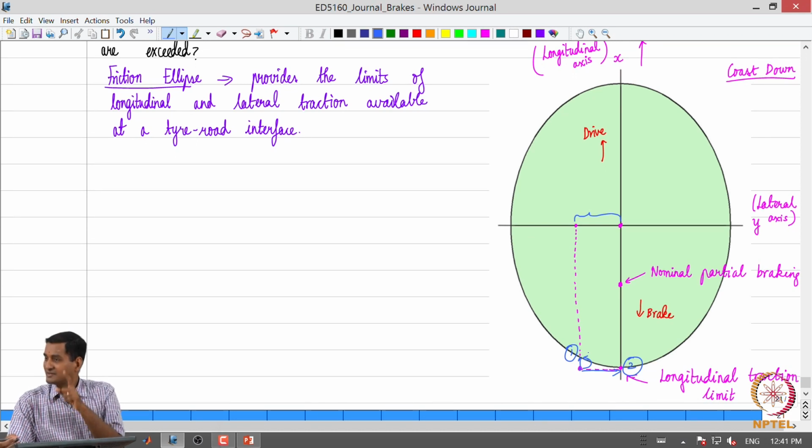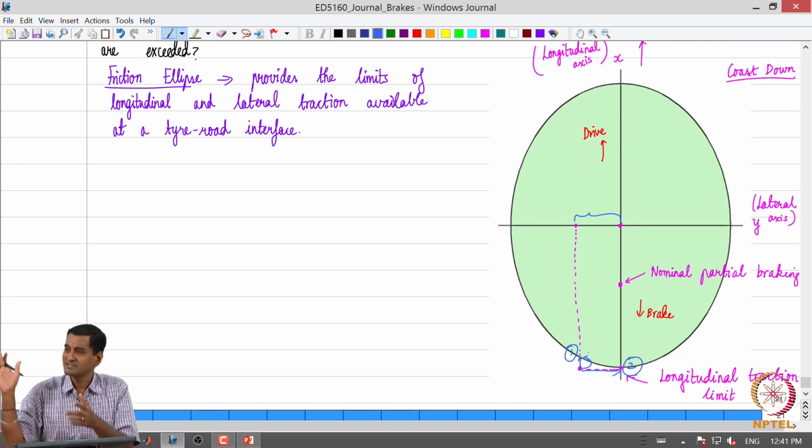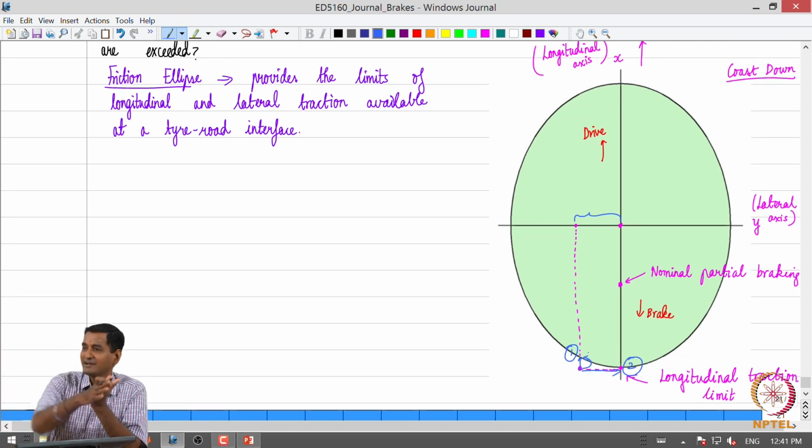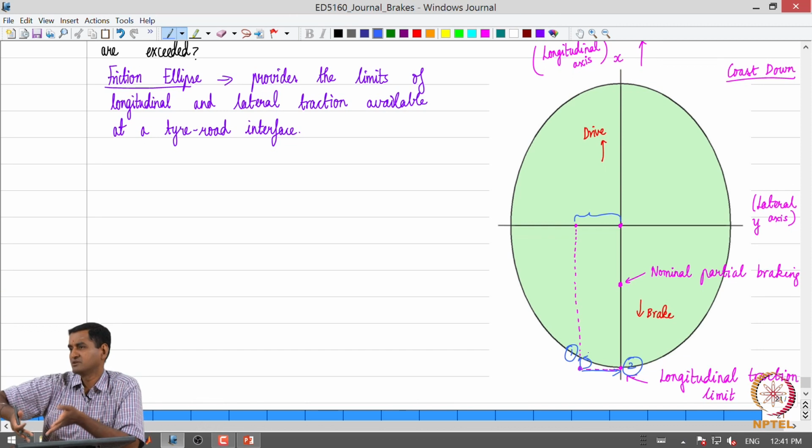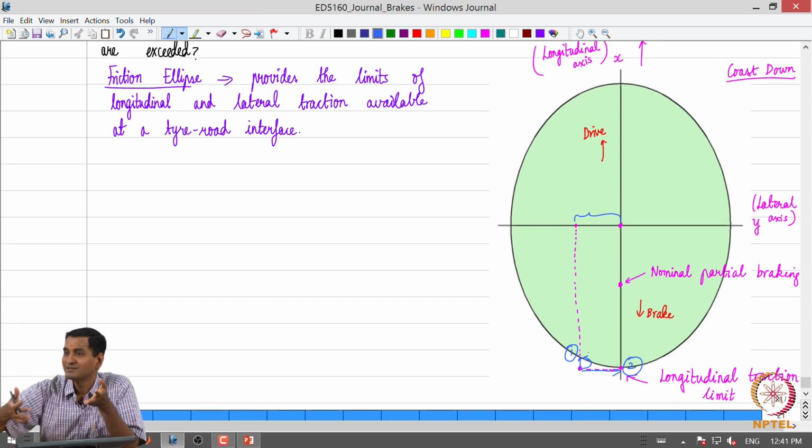Okay. So the driver commands some brake pressure, because in this experiment I slam the brake, right. I want the maximum operating pressure, but it so happens that I cannot sustain that, so it has reduced it. Okay. So that is the task of an anti-lock brake system.